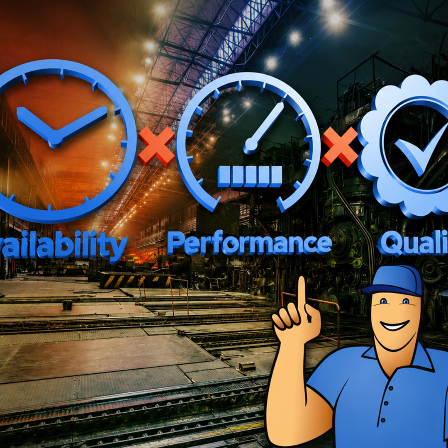That's not uncommon. Often, small things happen that get forgotten or swept under the rug because they seem unimportant. I've seen this dozens of times in my 36-plus years of experience. I'd recommend starting with evaluating and fixing equipment reliability issues and implementing a basic, yet thorough, preventive maintenance schedule. Make sure each machine is running optimally, and you may discover your numbers starting to go up. In fact, you may see your OEE number reach close to 75% by doing this easy step.